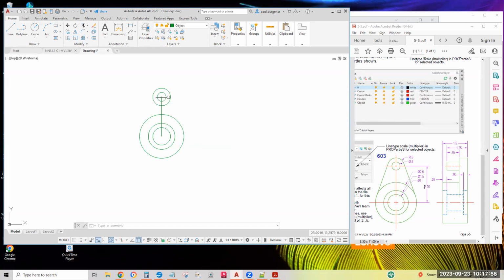I'm going to use the mirror command. I believe we've covered the mirror command. So I'll draw one tangent to tangent line and then mirror it across. For just 2 tangent points, I'm going to use 2 OSNAP overrides. If it were 4, like the serpentine fan belt exercise, then I'd change my OSNAPs to only tangent, and then remember to immediately set them back to the 5 after I'm drawing tangent to tangent lines. But with just 2, I'll use OSNAP overrides.